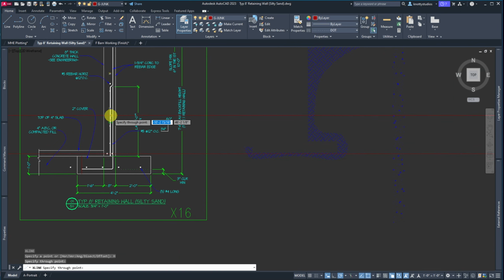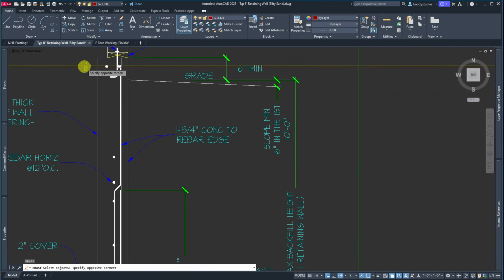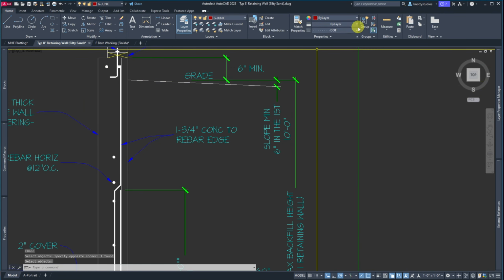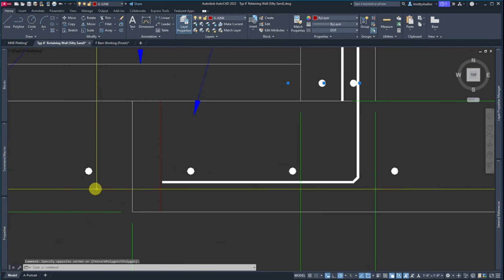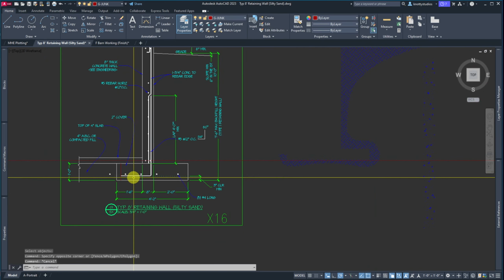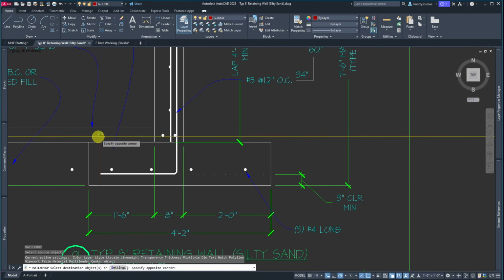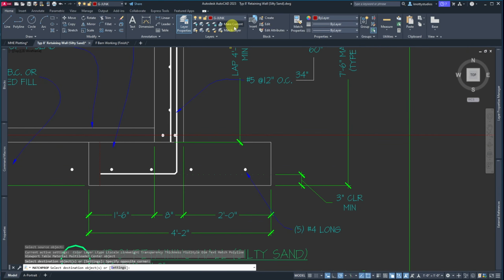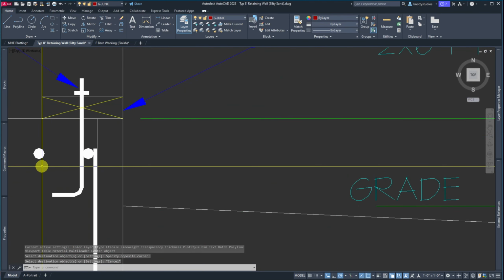I like that name too. And then come up here. It's doing a dot. I didn't notice that. That didn't go in the middle. I don't know why this is set to dot, but by layer. And so this guy, that one's okay. In fact, you can just do, if you want, MA. Boom. Boom. But this one is set to by layer now, so new ones will draw correctly.